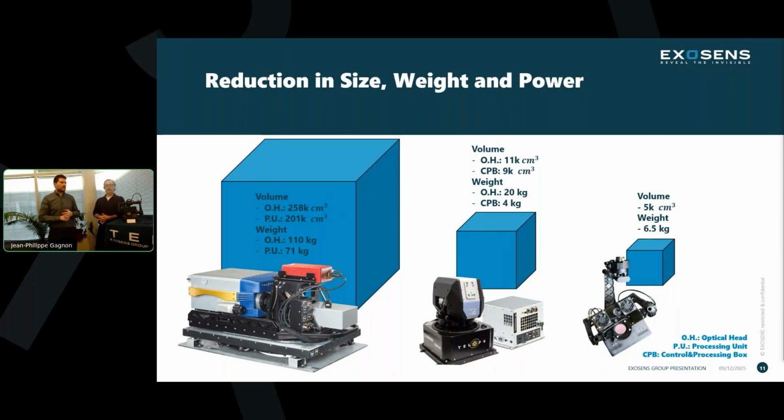So talk about the detector, which, like GB said, is not a 320 by 256. Now it's 320 by 160. That's because of the smaller size; the interferometer, even the entrance window, was all looked at optically. One big challenge for everyone was the heat dissipation, because you have such a small system. Obviously, you have to manage the heat. That was a big factor here for the Hypercam Nano. So the R&D team worked really hard on that, and we are proud of it today for sure.